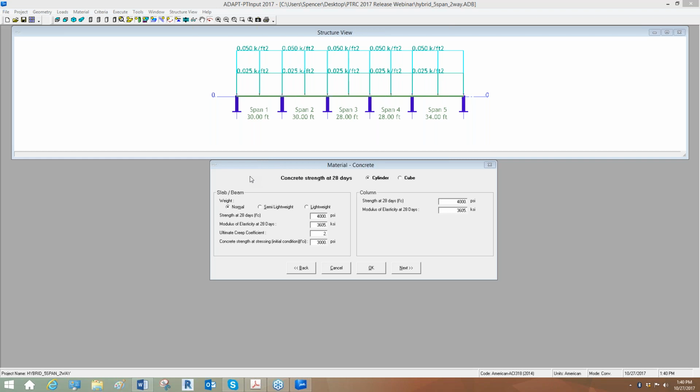The next question: in parking garages, is there a provision for progressive collapse against deteriorated tendons? No, we don't have any input in the program relative to the deterioration, or let's say the loss of strength for a tendon. The user could always adjust the effective force or adjust tendon parameters to account for that, but it would have to happen in multiple models that each consider the effect over some period of time at some station along that time period.